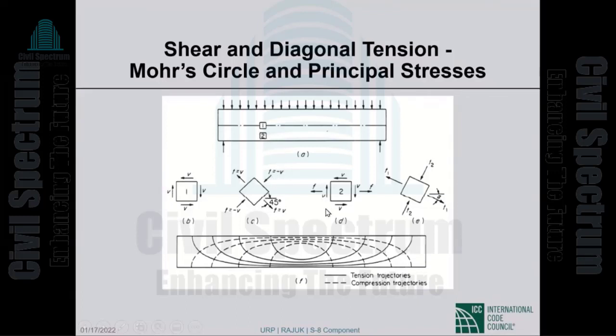On this element, we have bending stresses and shear stresses that will give us principal stresses as shown in the second picture, inclined at some angle, okay, not 45 degrees, some angle lower than 45 degrees. Now, if we plot sigma 1 along the length of the beam, we will get the lines that are solid lines in the picture. And if we plot sigma sub 2, the compression stresses along the length of the beam, we will get the dotted lines.